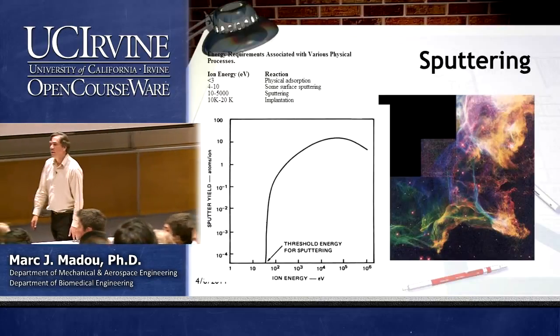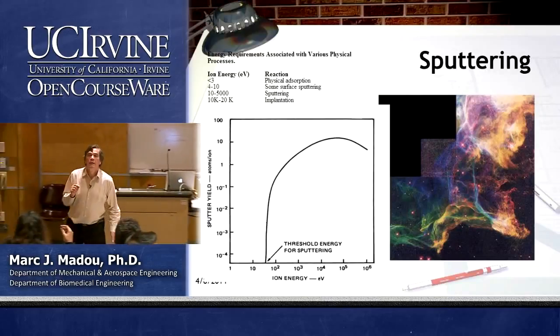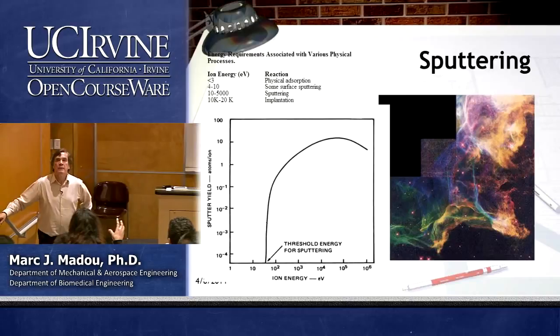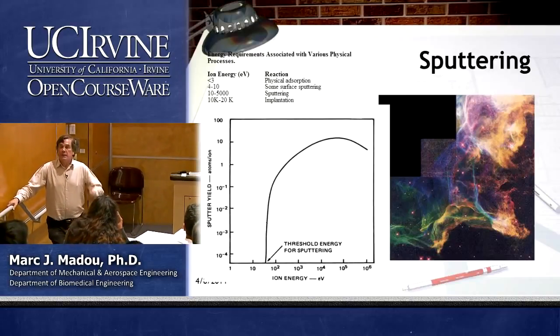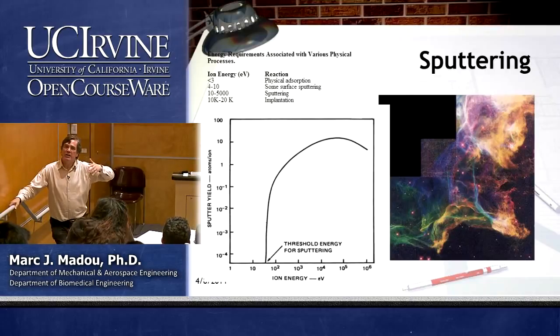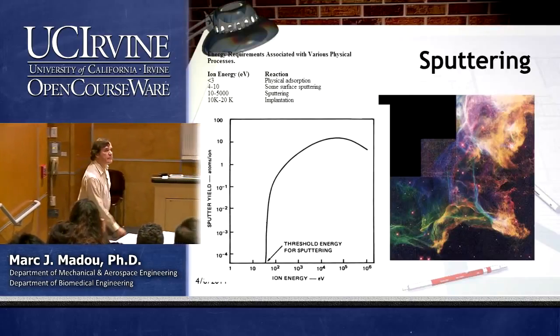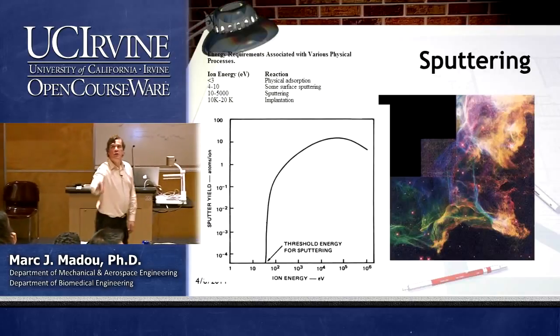For the USM, why is there no heat generated? Wouldn't the slurry cause friction between the workpiece and generator? Well, there's the slurry, and the energy you put in it is not high enough. The rate is not high enough. It's a slow technique, right? But it's a good question, yeah.